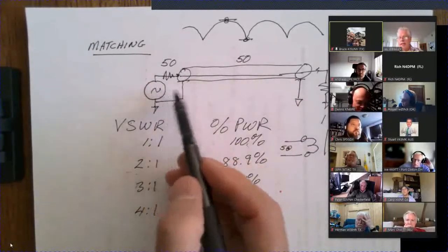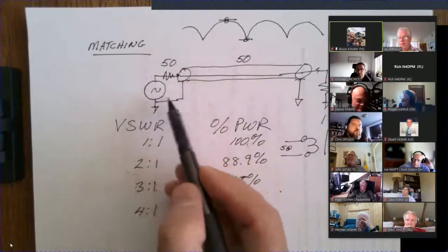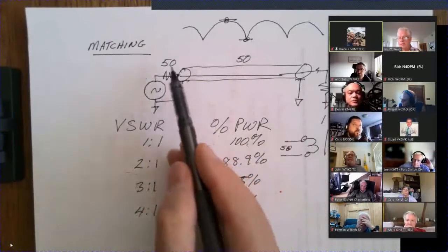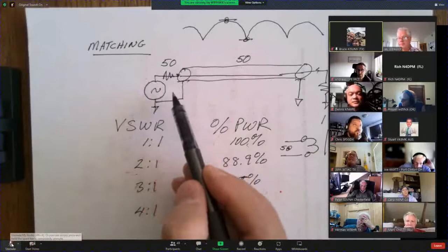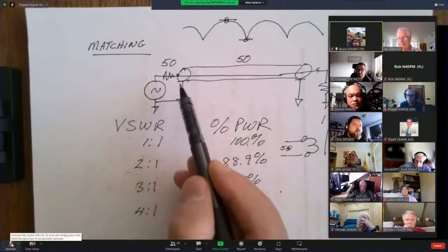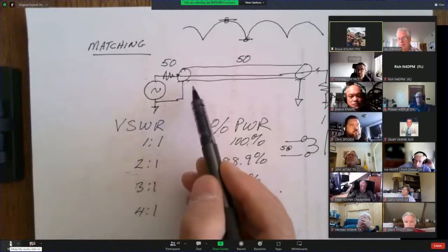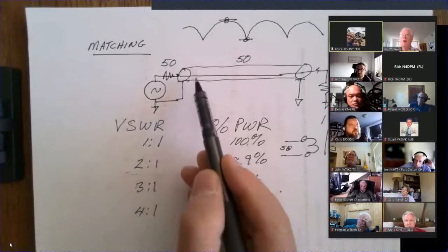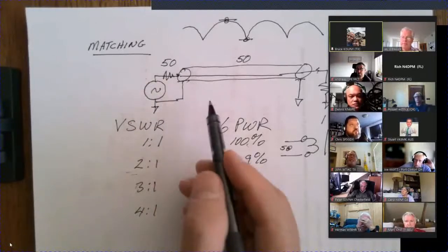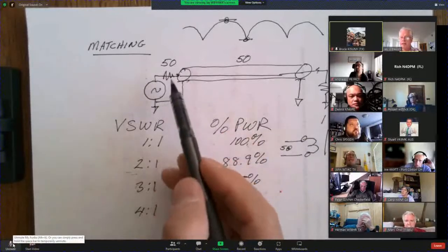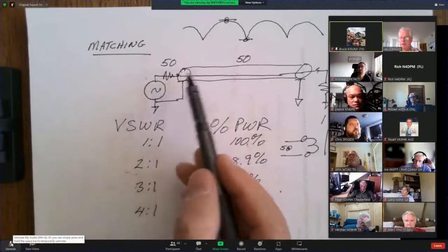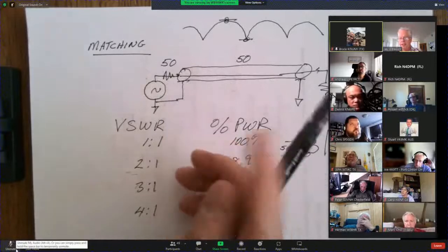How are you connecting this when you have the transmitter? Where's the transmitter being connected? I just connect the antenna cable, disconnected from the Rig Expert, connected to the transmitter itself. I see. And your cable remains. So the radio rig is measuring a different SWR than the Rig Expert. That's right. Gotcha. That's correct.